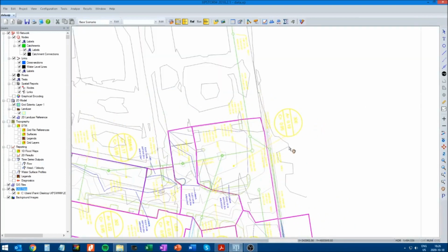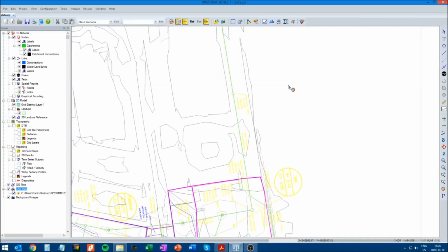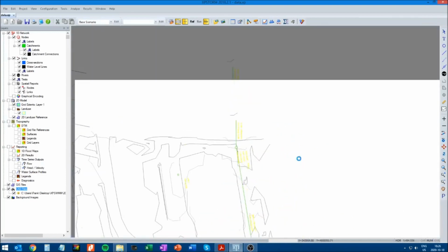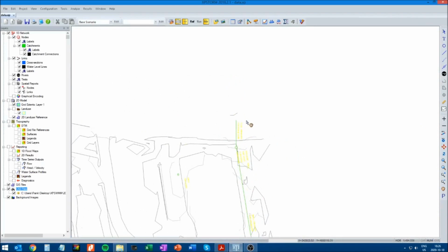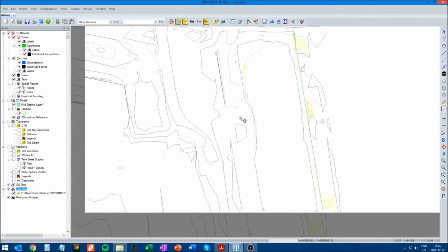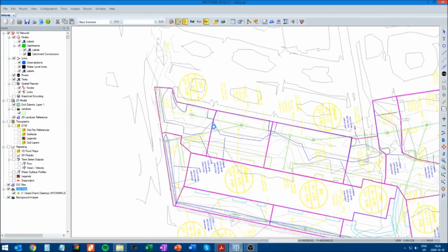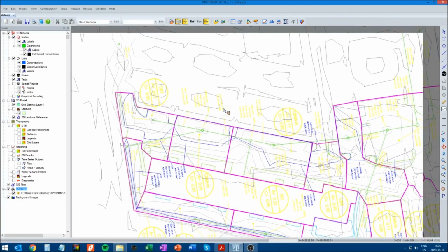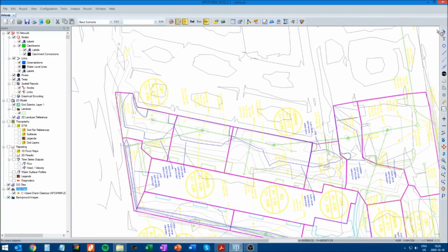Together with some uncontrolled flow, the sewer will connect to an existing storm sewer system, which is not shown here, but it's running perpendicular to the connection, along here. We'll be ending the model at this point, so we don't really need to see the existing storm sewer on this drawing. So we'll start tracing out the storm sewer system.